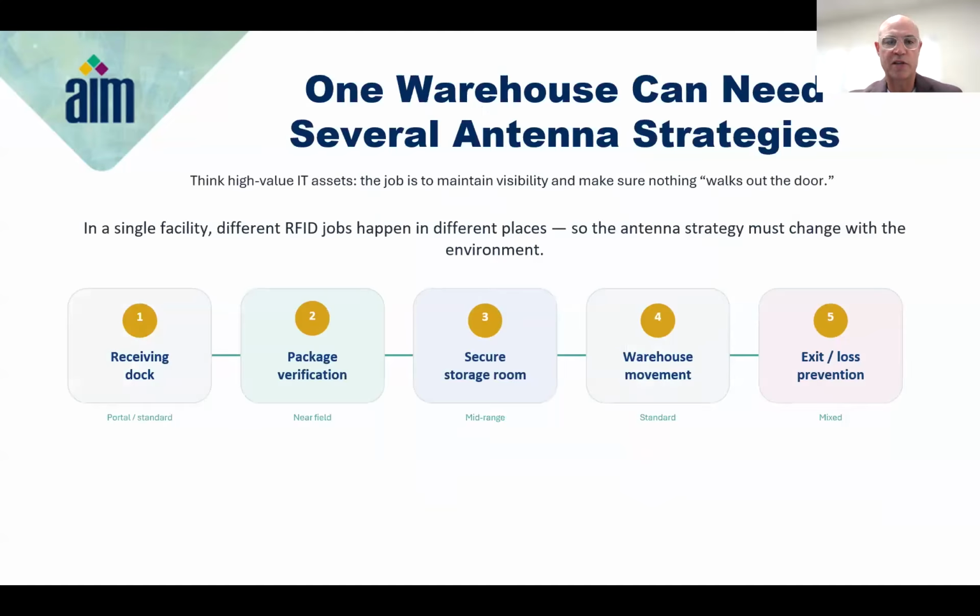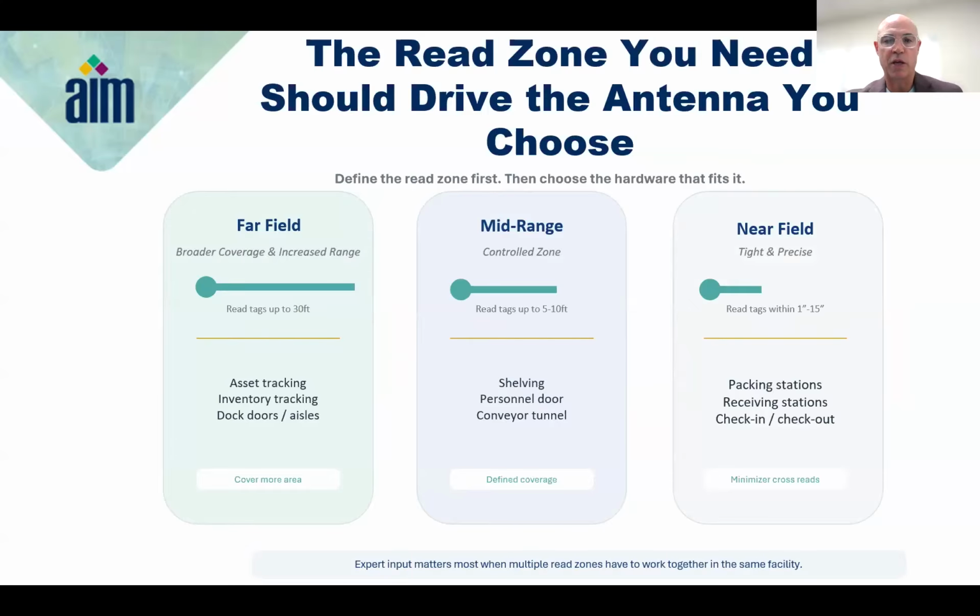Oh, let me just ask here, Chris Brown, following up: can you get 15 inches with inductive coupling? Seems far. So the answer is yes, I've seen it done, and it has to do with the size of a near field antenna. If you use smaller near field antennas, typically it pushes more energy straight up and there's less loss to the sides. I've seen a 1 foot by 2 foot antenna read 10 or 12 inches off the surface of the antenna.